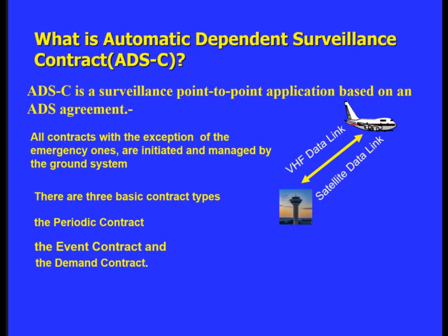The waypoint change event is triggered if the next or the next plus one waypoint is different from what had been intended. This change normally occurs due to normal waypoint sequencing by the flight management system of the aircraft. The next or next plus one waypoint can be either an ATS waypoint or a pilot inserted waypoint.